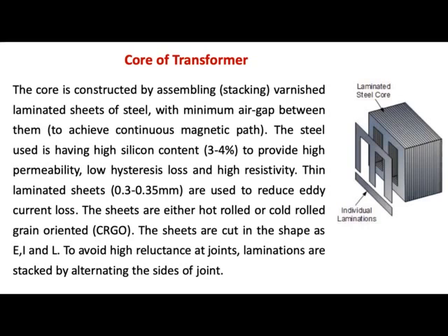Then, because the core is made of multiple sections, the air gap needs to be distributed throughout the stacking of the material, because if the air gap is concentrated at one place, the MMF required to build the same flux will be much more, because the reluctance of the path will increase. So we distribute the air gap such that the reluctance of the path is kept to the minimum and the flux can be produced by a small MMF.